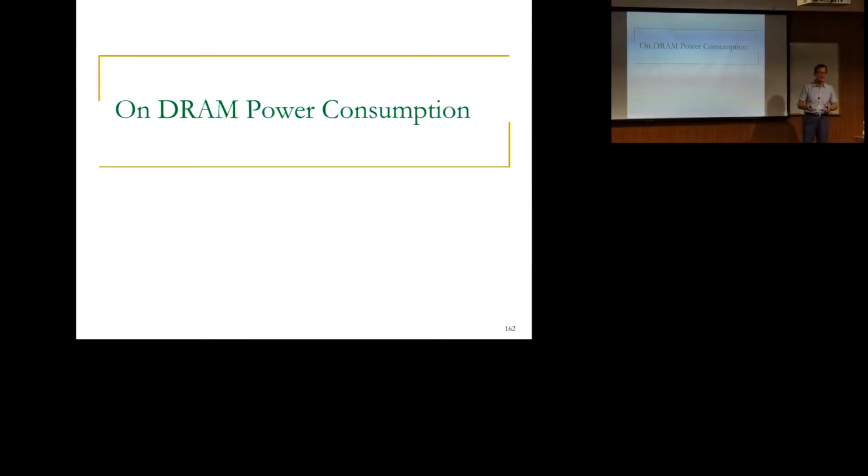And we always relied on power models that were developed in the past, which are usually based on either some sort of circuit level simulation or datasheet values. DRAM manufacturers publish these datasheet values where they actually say, this is the current drawn by this activity, for example, a refresh. This is the current drawn if you do an activate. This is the current for a read. So they have these 9 or 10 different current values in the data sheets. And the question always is, how reliable are those values? It's written in those data sheets, but how reliable are they? And that's exactly what we tried to answer.